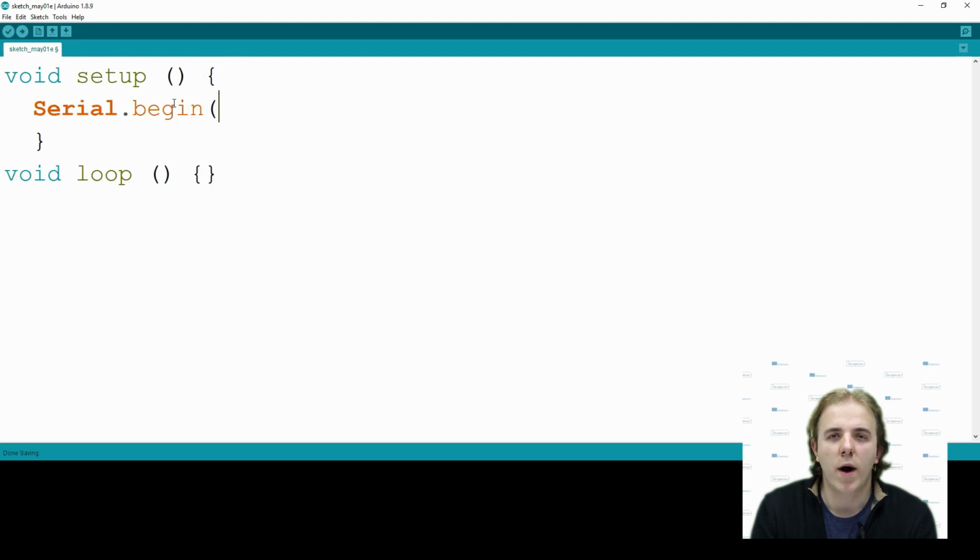To demonstrate how while loop works, we will write a simple program that prints out loop cycle number. First, enable serial communication, and in the main loop make a variable. Write a while keyword, parentheses and brackets. In parentheses, write a condition. We will compare our variable to a threshold value. While our variable is less than the threshold value, the code in brackets will be executed. When the variable is greater than the threshold, the cycle will stop.